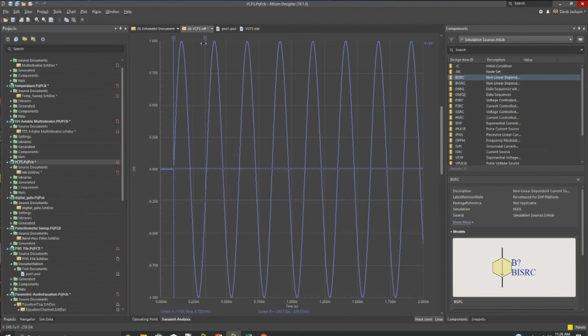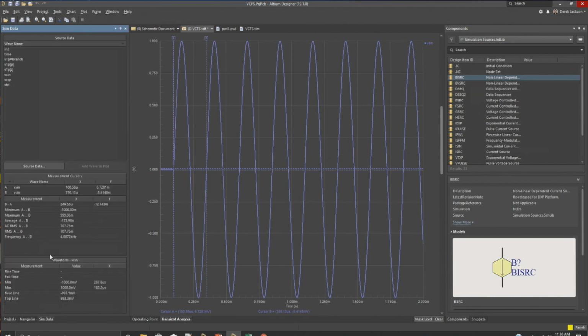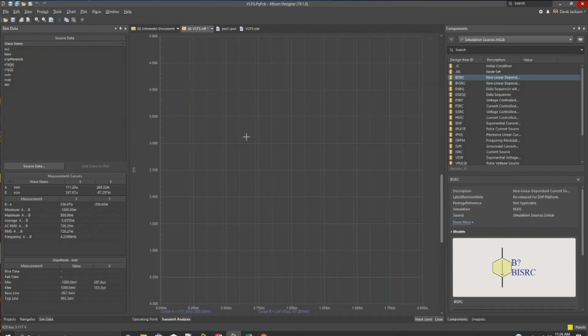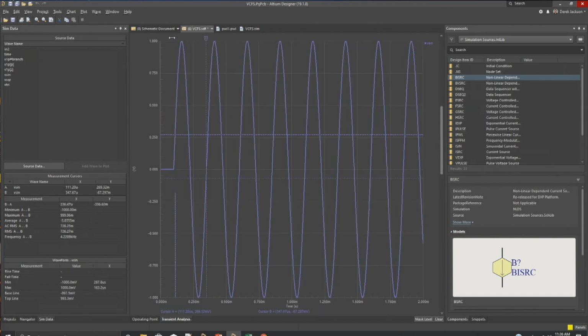If I want to get it right at the 0 point, it's a little more tricky, because we want to get these at 0. You can come in and change the point on here. So if I just type in 0, I went all the way to 0, 0. But sometimes you can manipulate those a little bit. You can use your left and right arrow keys. Because you want to get right at the 0 crossing there.